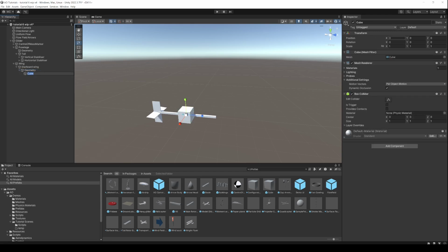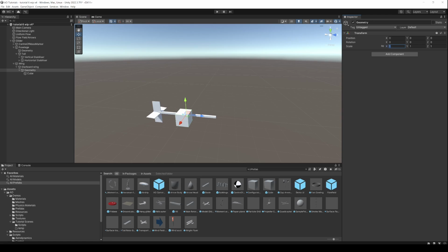What we're going to do is offset this by 0.5, and this means we're just building on one side of the aircraft. You can see why we've done that in a minute. We are going to have this semi-span be 3 meters, and it's going to be 0.05 centimeters thick. We're also going to shift it back half a meter, and the reason we're doing that is so that our root object for the wing is at the leading edge. It's good practice when you're doing aircraft models to use a reference point for all the dimensions, and typically the best place for this is the leading edge of the wing.